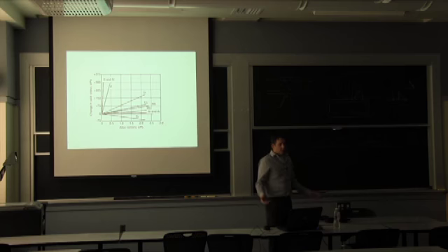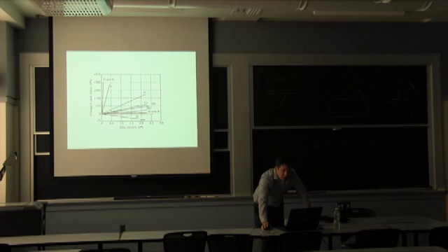Now, there are other ways to strengthen steel. So we talked about the carbon here. This is showing how much you need to add of an element to change the yield strength. So when you see the positive slope, that's carbon and nitrogen. You have phosphorus. It's very rare we use phosphorus for strengthening, but it does have a strengthening effect. Silicon, copper, manganese we use a lot for strengthening. Molybdenum is more expensive, so we use it mostly for corrosion resistance. When you get into stainless steel, we can use it also for strength. And chromium is reducing the strength.